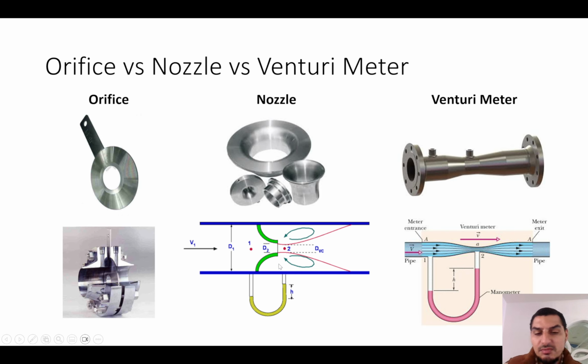We are measuring it a little bit after this. And this is what we mentioned before as well about the vena contracta, about the entrance region. So we have also a vena contracta here. So this area is smaller than A naught, and the same here. So this is also accounted for using the coefficient of discharge.